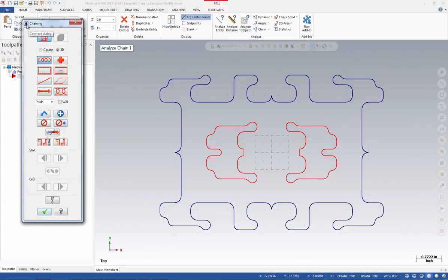Once this is done, make sure that the dialog box is expanded like so. You'll notice at the top we have the choice between wireframe and solid. Solid is shaded out because there are currently no solids on screen, so we'll have to use wireframe. Below this is 3D and C-plane or construction plane. With 3D, this will use the XYZ plane, whereas C-plane will use the XY plane.